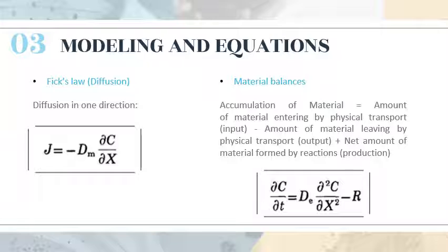The key parameter in Fick's law is the molecular diffusivity. This coefficient has been measured for a number of compounds and can be estimated for other ones. It is important to recognize the difference between the application of Fick's law to free diffusion and diffusion within a porous solid. In a porous solid, the molecules move through pure water by molecular diffusion.